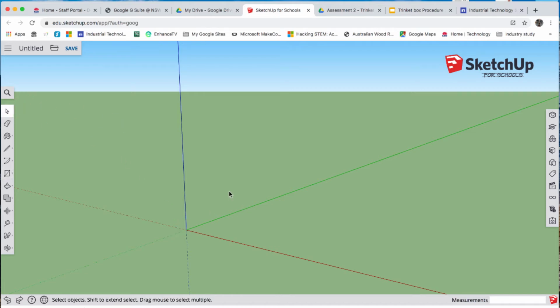So I've got nothing selected at the moment. I'm going to use the keyboard shortcut R, click, drag, release, 220, 12, enter. Okay, so I can zoom in on this a couple of different ways.